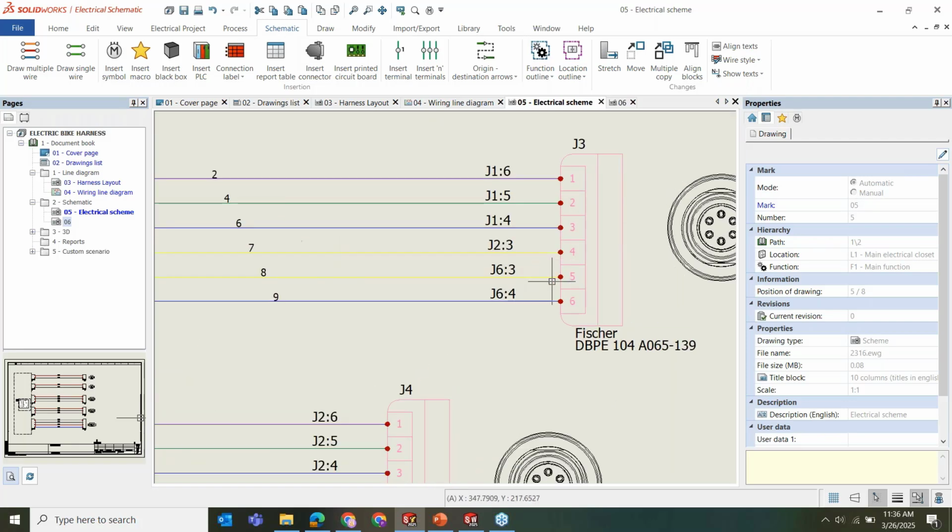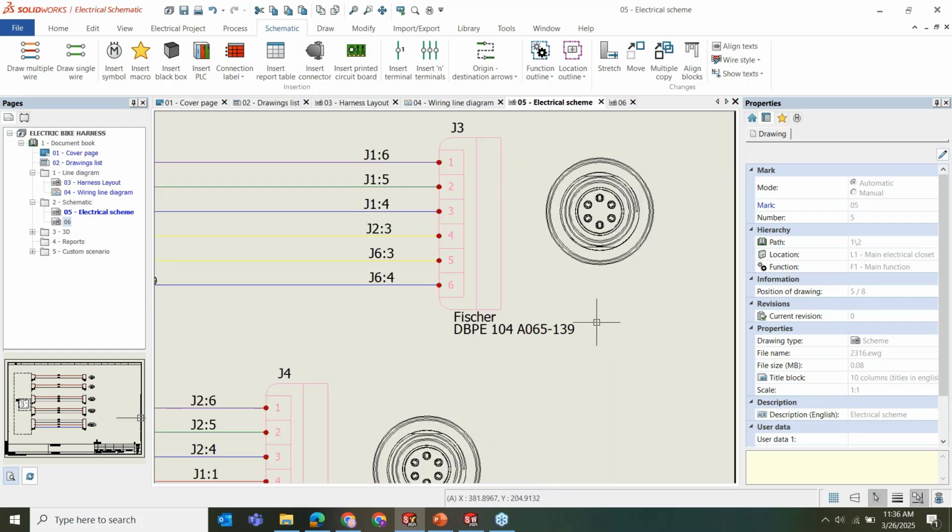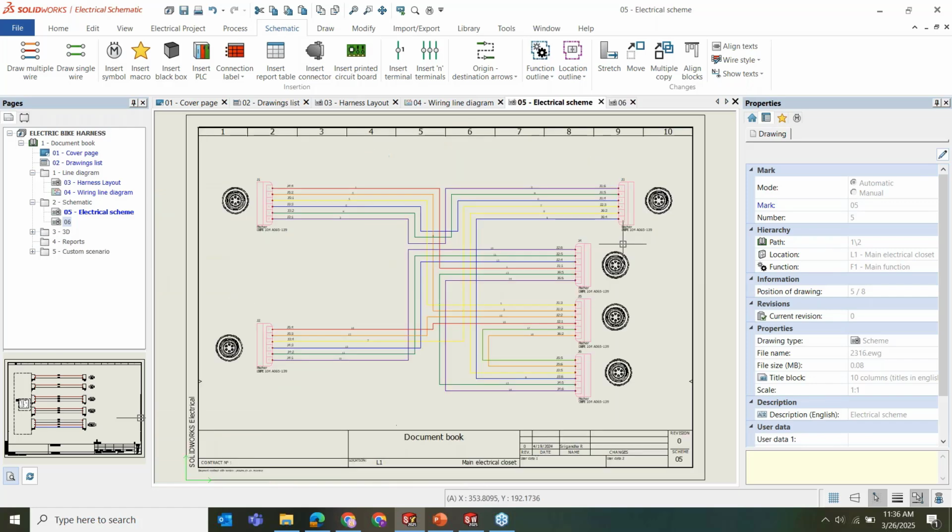So if I have this, you can see this is showing as 1, 2, 3, 4, 5, 6. If you wanted a seventh one, then you can just copy and edit it and then save it as a different name with the seventh one as required. And you can see here on the right hand side, the cross section of the connector. This cross section is provided by the DWG I have imported from the original one. And this DWG, if I have generated it in SolidWorks also, I can insert it here as a library component. Okay. So these are the main things that are being done.